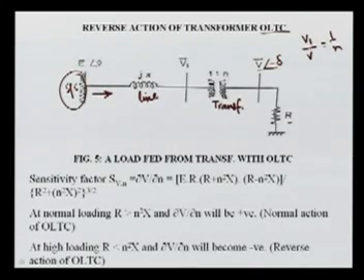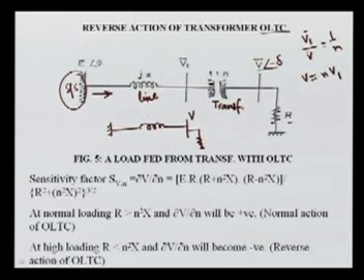So we are getting this ratio, and now this V will be nV1. Now we can represent the complete system. If we ignore the ideal transformer on this side, we can write here this is your line reactance, this is your V, this is your R, and this voltage will be transformed, and this is your j X n square.